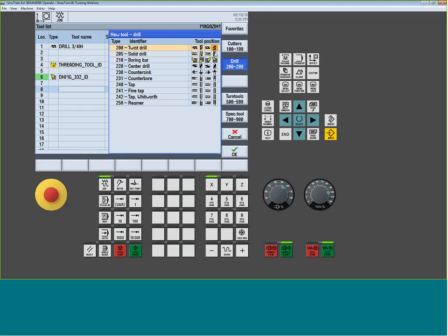I do have an inverse. Maybe I have a little right angle head and I'm tucking up inside of a bore. You can build a drill for that. But certainly 95% of the time, maybe even higher, I'm just going to use this first position. Now, nothing here is denoting whether this is a static drill, so meaning it doesn't spin because you're spinning the part with the main spindle, or a live tool, meaning the spindle would be held rigid, and then I could drill off-center for like bolt hole patterns, face patterns.